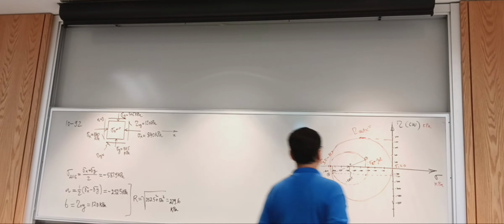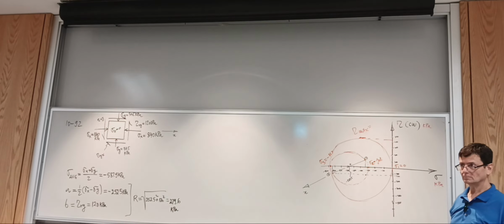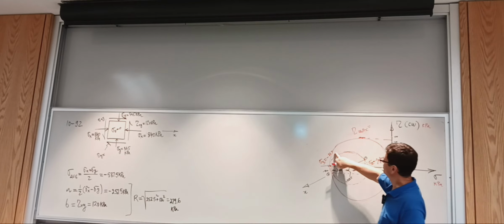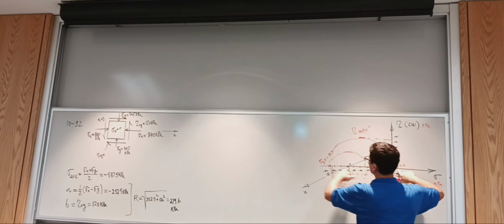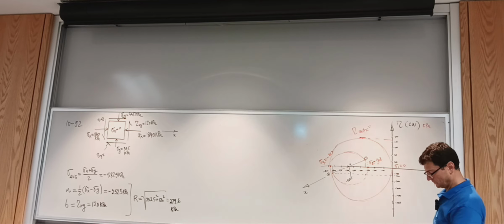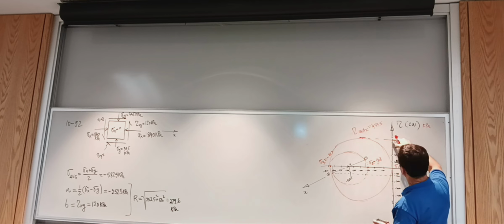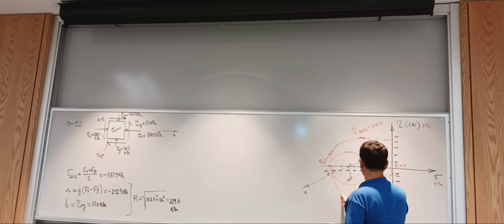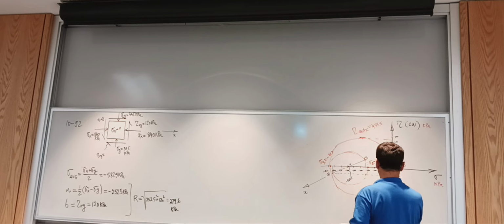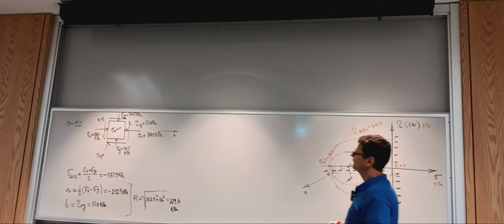So what is tau max from the figure? Well, you take this and divide by 2. So it will be sigma 1 minus sigma 3 divided by 2, and sigma 1 is 0, so it's 867 divided by 2, which is 433.5. Yeah, I almost got it, if I adjust it a little bit. So yeah, we've got tau max, the true tau max.